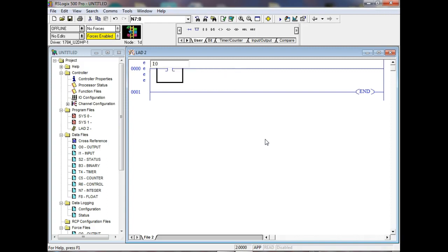This is in module 0, so what comes next is module 0. And then we put a dot, and then we would put a word number, and then we put a slash, and then we put a bit. Now, the problem is the word number depends on the module. If the module does not have multiple words on it, then the word number is optional.